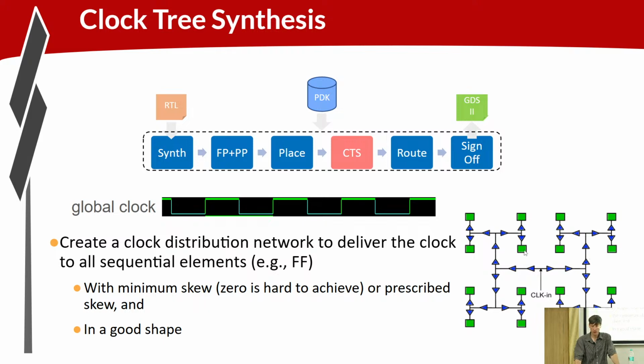And to do that, we usually create structures that look something like this, which for what I hope are obvious reasons is referred to as an H tree, right? You can see the H at the top level here. This H is sort of a fractal: break that H down into the next level H, flipped on its side, break that down to another H. This way, the path to every one of these leaf cells is the same distance. So you can keep the skew minimal that way.